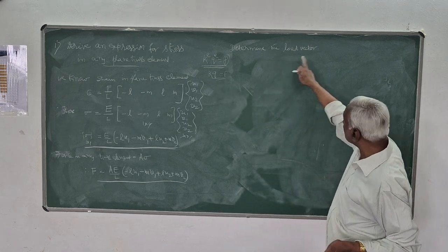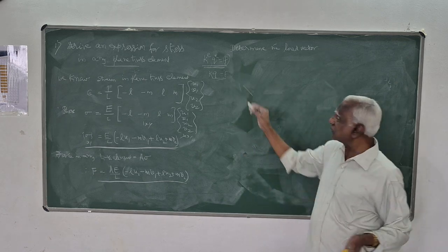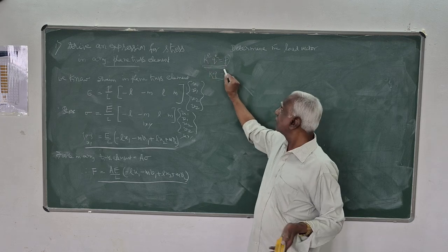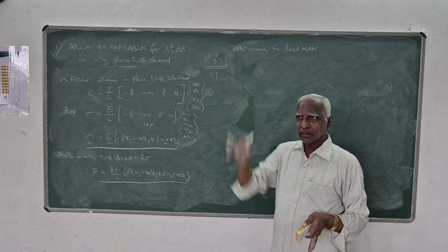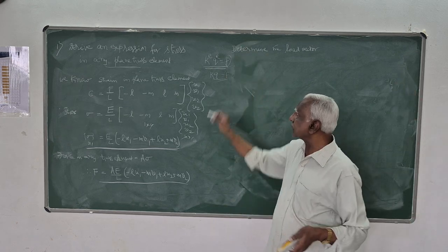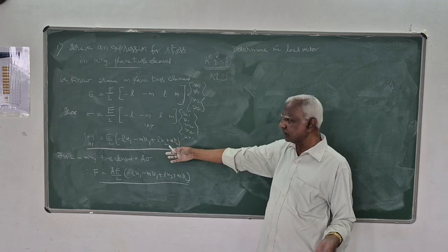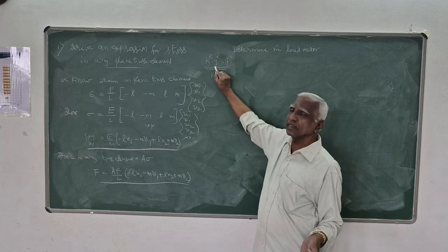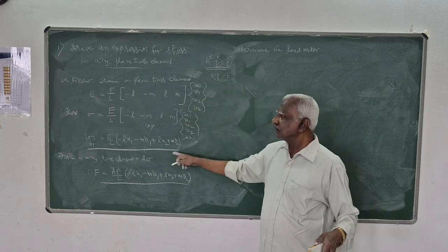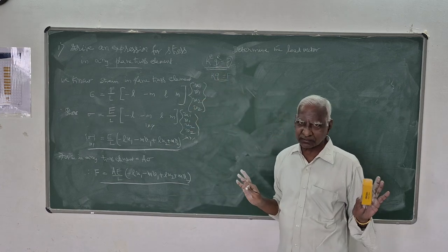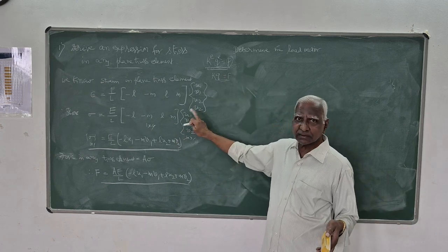Now, I will determine the load vector, this right hand side. I told you how to determine this K. How to determine this load vector? The given load is always in global coordinates. The given load will always be in the global direction. And of course, using these two, this also you can determine. I have given the expression now. The only unknown is this, that you can solve for the structure. Then once you know all those displacements, you can find the stresses or forces. That's the final step.